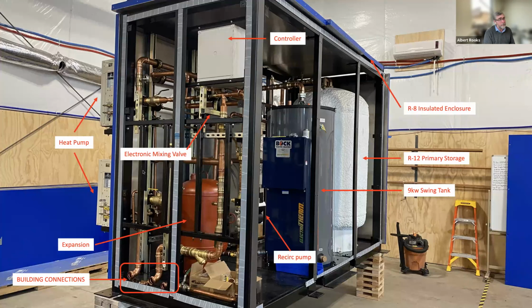So that would be a larger heat pump like a Mitsubishi 40 kilowatt, or one of the larger Lars systems, or any of the new CO2 large plants. The stuff that we do is really a potable system all the way through. And so I've got it way north in Smithers, BC. And every year the challenge there is to keep the defrost from freezing up and causing a problem with the system. And that's about as cold as we want to do with a potable system.